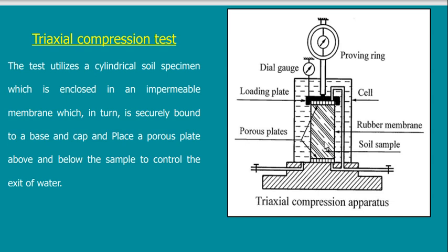I will allow water to leave the sample. It is as if I am acting that this sample is sand. But if I keep this tap closed, then I am resembling a sample of clay where water is not free to leave. And this will be at the early start of the loading in reality.